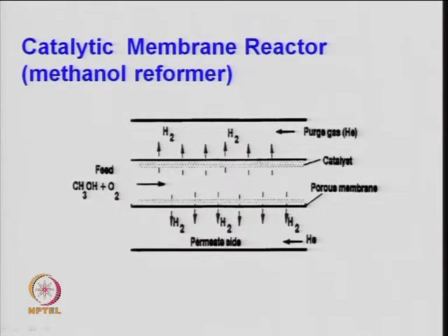So, one needs to check the optimum concentration or steam to hydrocarbon ratio for the process, right, but a very high amount of steam cannot be used because it unnecessarily dilutes the reactor and the reactor sizing will increase, right. So, one needs to check that. So, new trends are looked into.